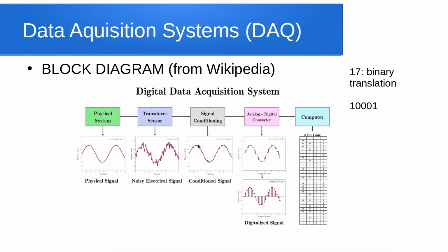Another version of embedded systems or even IoT systems that are used very much in the industry are the data acquisition systems. Basically, in data acquisition systems, there is a sensor which collects some kind of signal from the plant or the phenomena that is being observed. The sensor translates that physical signal into a signal, which is then conditioned, like linearization, filtering, and all that stuff.